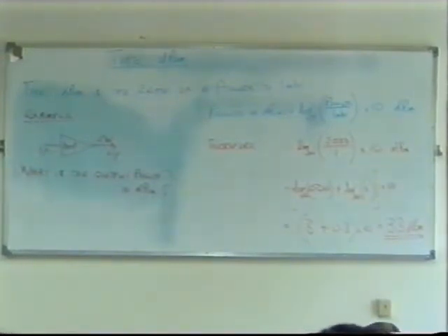Yeah, this actually brings out the whole point of why we use dBs. In other words, why don't we just say the gain of an amplifier is 100 or 1,000, instead of using decibels? The answer really has to do with the way we're using the power. Initially, you're probably aware that decibels, the measurement of dBs, were first used to measure sound, how loud a sound was.